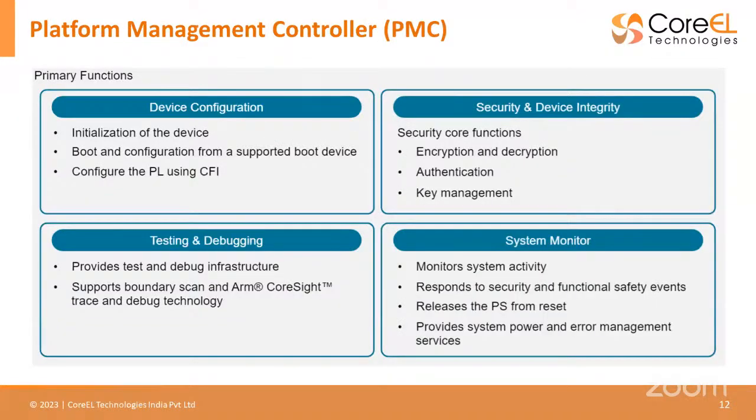Then you have the PMC, which is the platform management controller, which is taking care of the complete chip, right? All the way from your device configuration, how you want to boot your device, where you want to put your algorithm, whether you're working in the PL or AI engines or DSP engines, all of that configuration, along with your device security, device integrity, and your authentication.